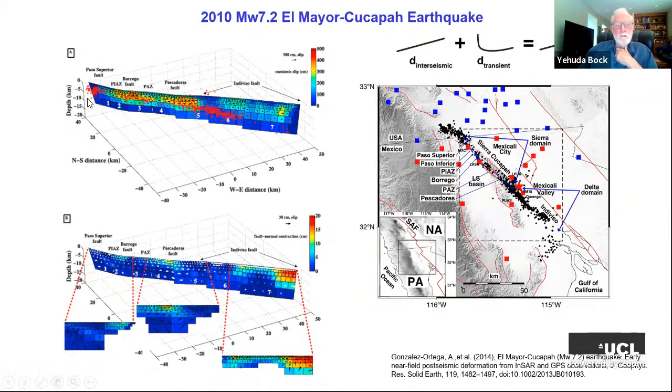And the fault inversion then allows you to determine the sense of slip and the amount of slip, that's how much it moves during the earthquake itself and in the post-seismic period. Right. And then there are also models for how the crust is moving linearly over time. So there's the co-seismic, which is at the rupture, there's the post-seismic, and then there's the interseismic period where the crust is accumulating strain until the next event.